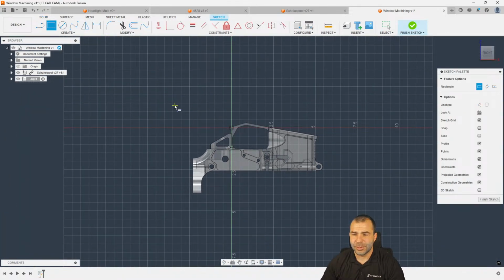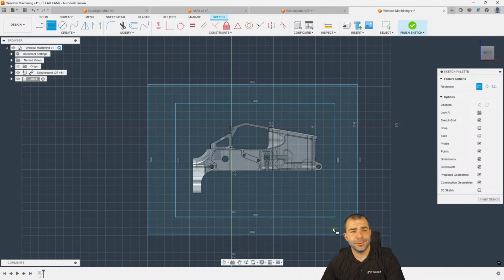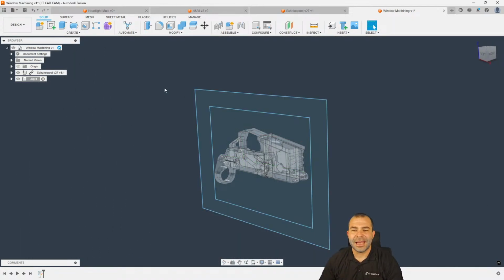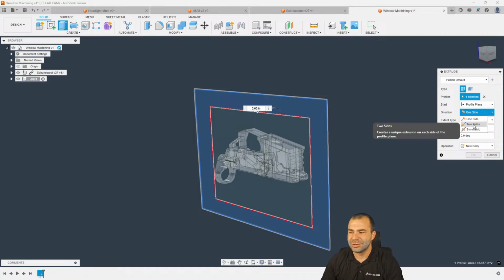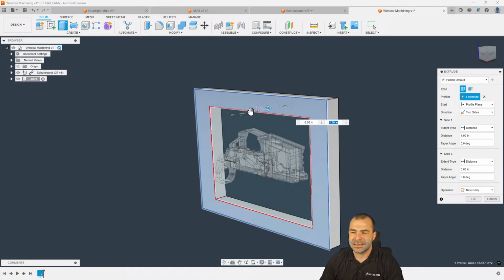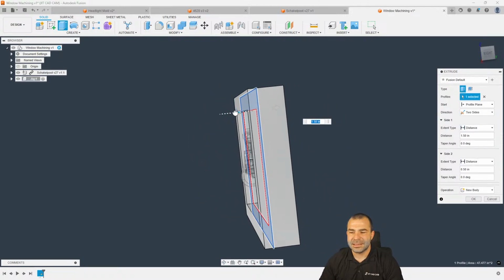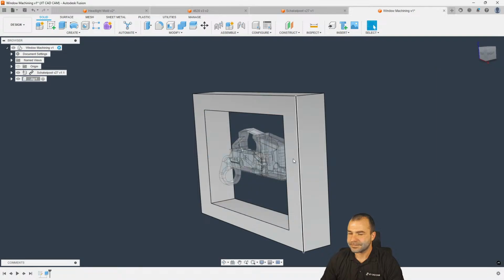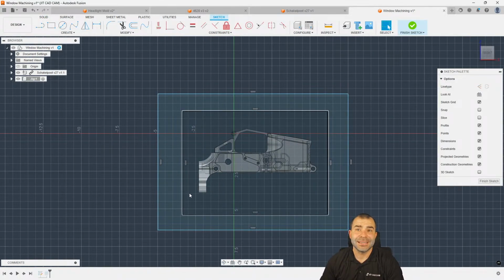And in this case, we were talking about window machining. So what I would do is I would draw my window. Again, I'm going to do this real rough for you guys so we can make sure we can keep these questions coming through. But the idea is I am now constructing my jig or however I plan to use this jig. So in this case, let's say I want it this thickness. Again, keeping with that mindset that I need this to be the same size, if not bigger than the part I'm machining. And one thing I did forget, so we can go back, is adding things like tabs, right?